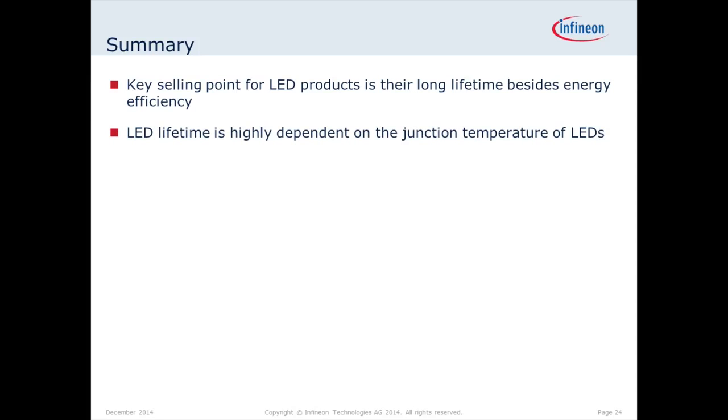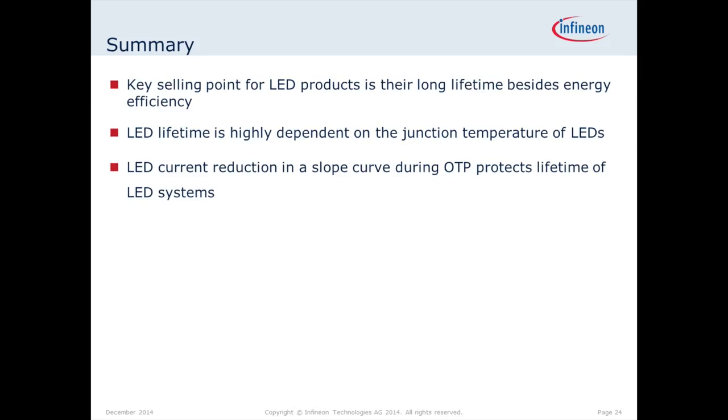Nevertheless, this LED lifetime is not given for free. If the temperature at which these LEDs are operated is high, then either the electrolytic caps can fail or the LEDs themselves. That means thermal protection is essential for LED lighting applications.